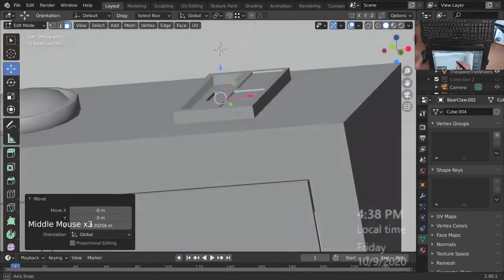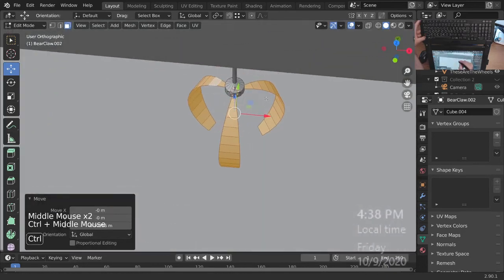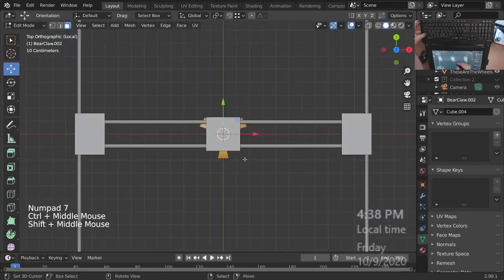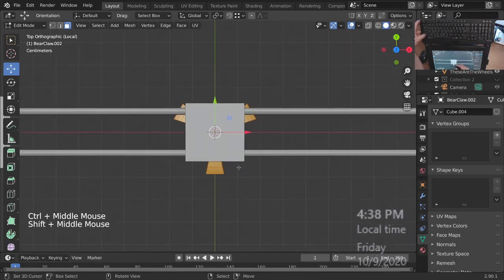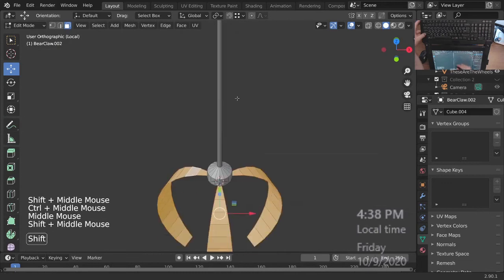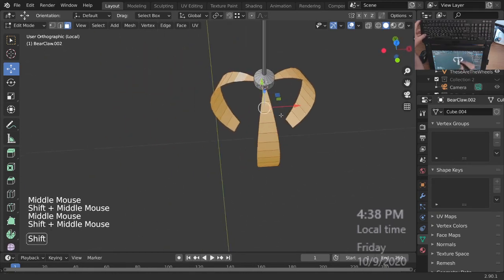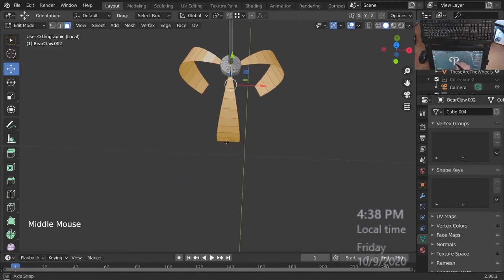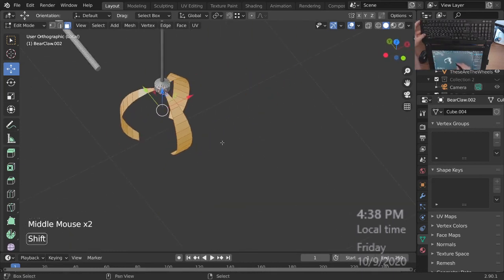All right, so what's going to be needed is, I'm looking right now for the best way to flatten some of these out, because obviously they're not in the same plane, there's no transform orientation on which I can work with. What I can do is create a circular array, basically work with one and do a circular array that gives me the rest.